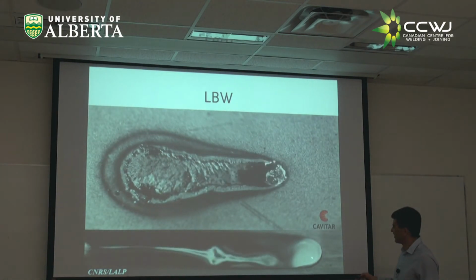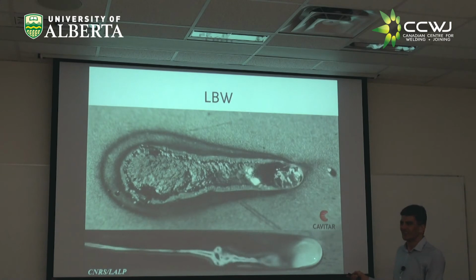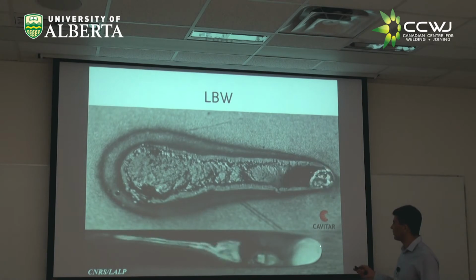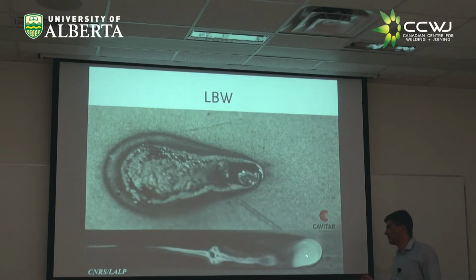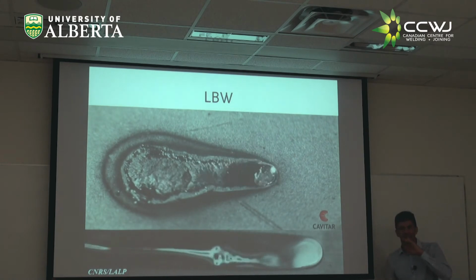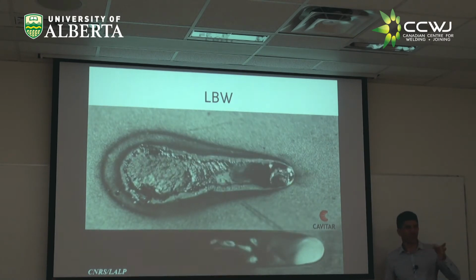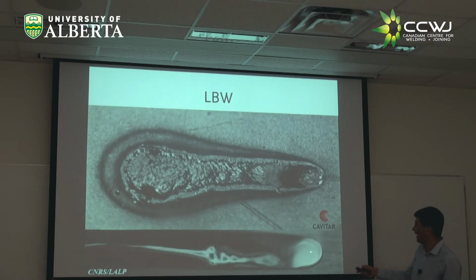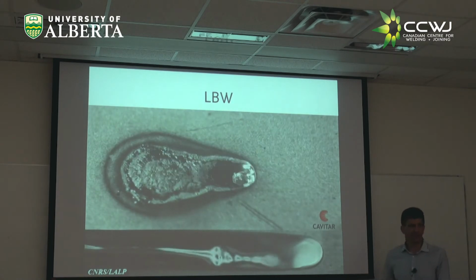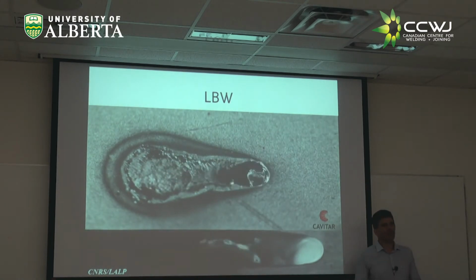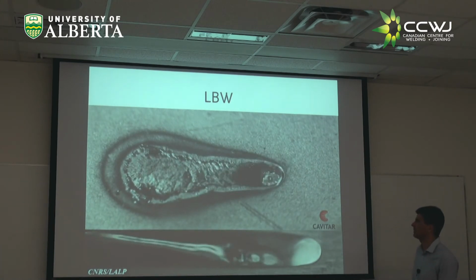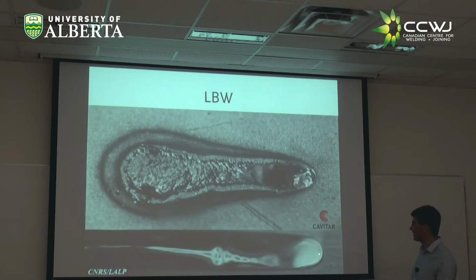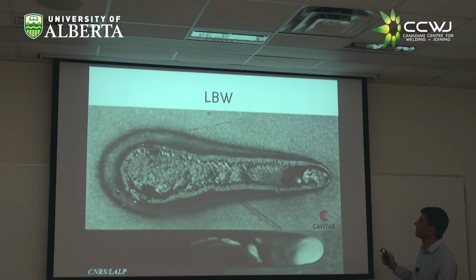Look at this other one here. Look how fast it's moving, right? This is a racing beam. What penetration mechanism do we have in this one at the bottom? Conduction, right? What people call conduction, but in reality the beam is hitting here, and the heat goes from the surface to the sides by convection. And conduction too, but convection is a big player. Very interesting, huh? Like nothing else you had seen. Okay.